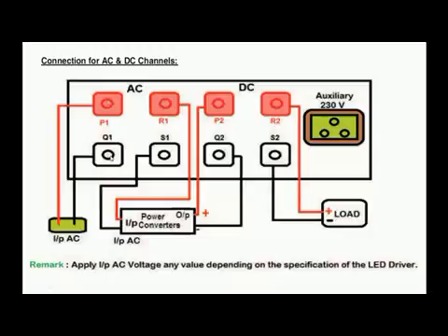This is the connection diagram for DTM-1. So these are the DTM-1 back terminals which are shown here. Here you can see the backplate of DTM-1, and this is the auxiliary supply 230 volts to power the meter itself. Now there are two inputs of AC voltage.